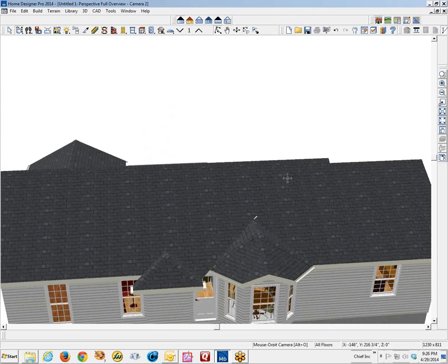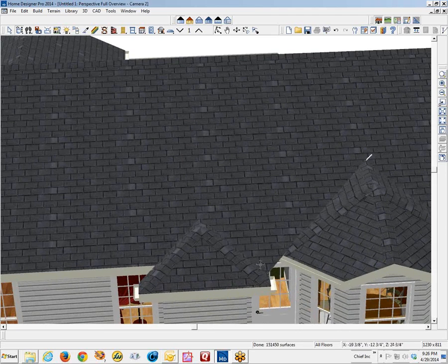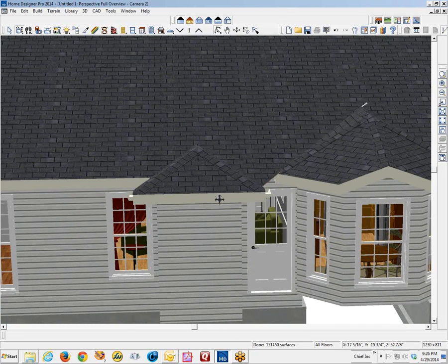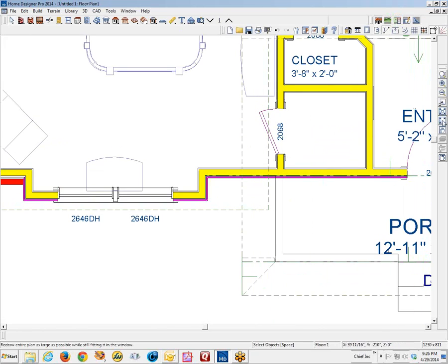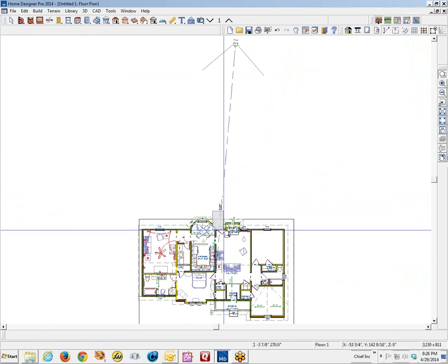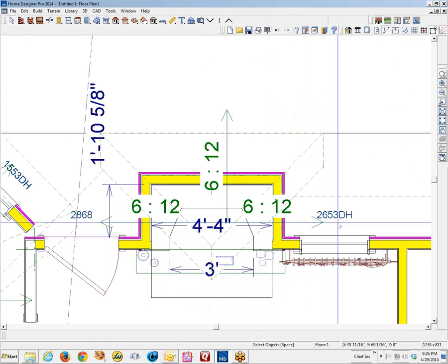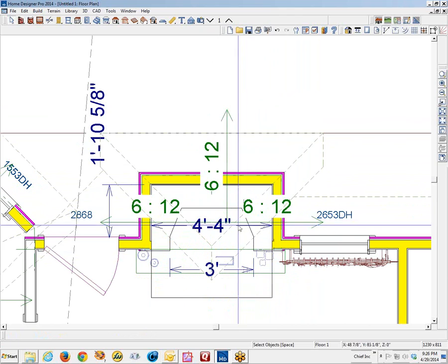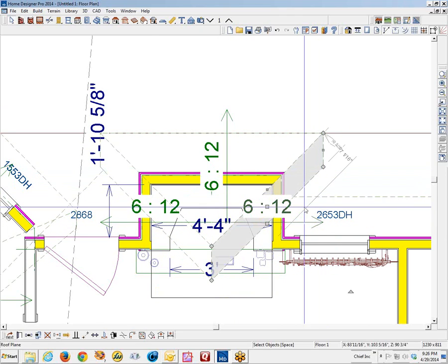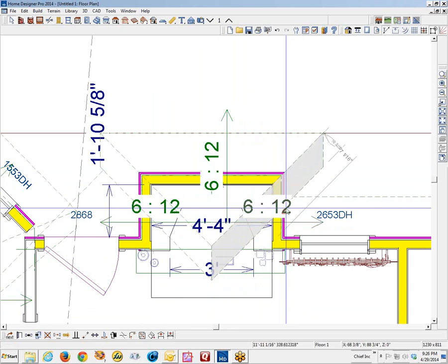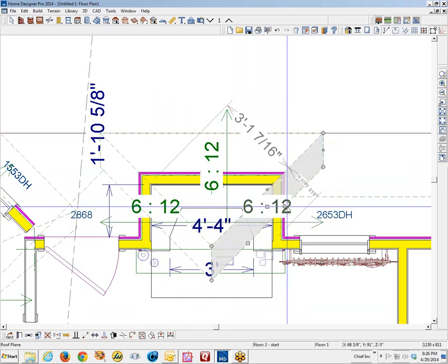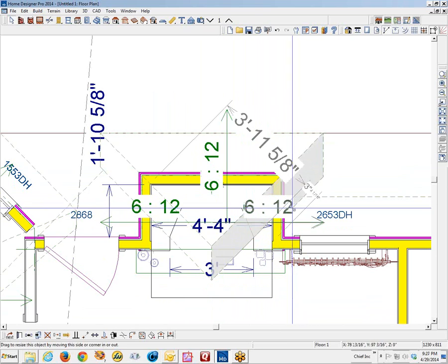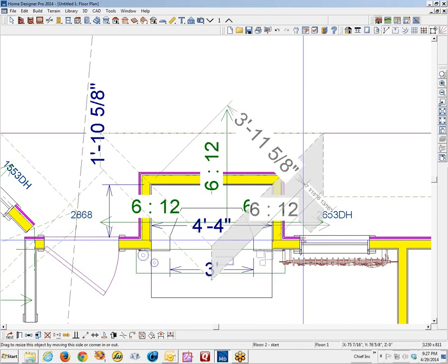Now the stuff in the back. It's really pretty straightforward. I just kind of glossed by this, how this all ties in. And if you want this roof here lower than the main roof, then this is probably all right, except for, let me go back there. Look at this in plan view. You can see there's a little space here, and if you're going to leave the roofs down here as you have them, I would click on them and use the break tool and put a break there just outside the siding.